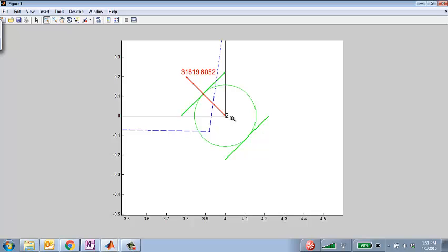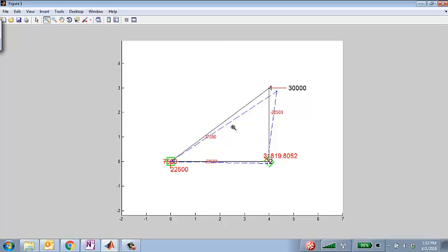If you use the 2D basic code that I gave you to run a similar inclined support problem, depending upon what input file you have, it may or may not work. But if it works, it will not give you the correct solution, something like this, okay? You do need to make those changes and use a different main file, the 2D Truss 2D with incline.m. You need to correctly fill it out and then use that file to solve problem 3.